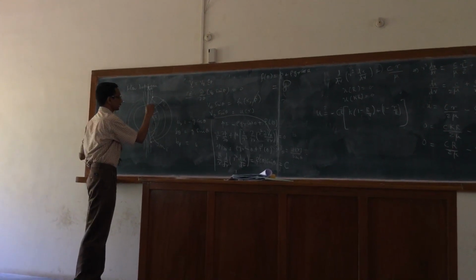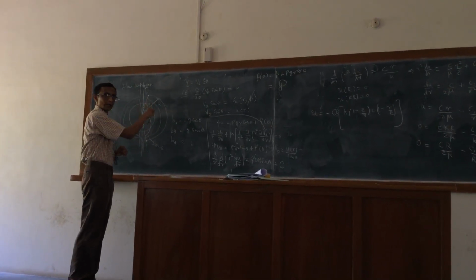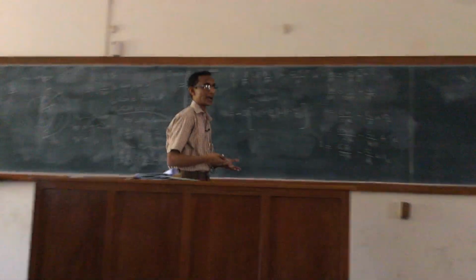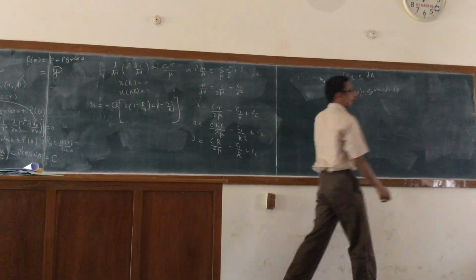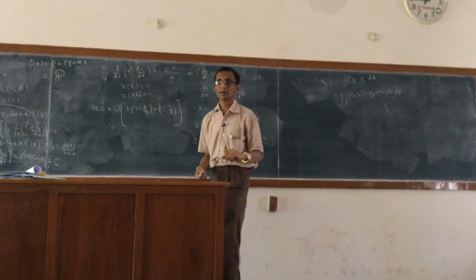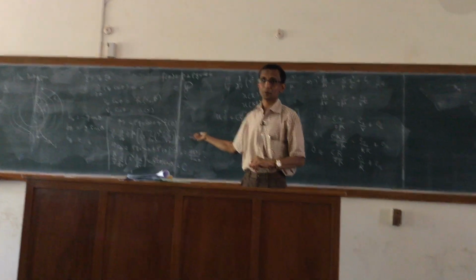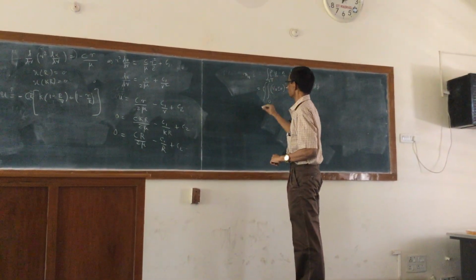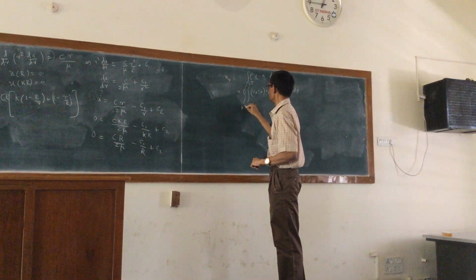So this is some theta, right? At what angle you calculate this flow rate, in general it might depend, but in this particular case it doesn't matter, because the sin theta here is going to get cancelled with the v_theta, which is inversely proportional to sin theta. So you can easily calculate; phi would obviously vary from 0 to 2 pi, and r goes from kr to r.